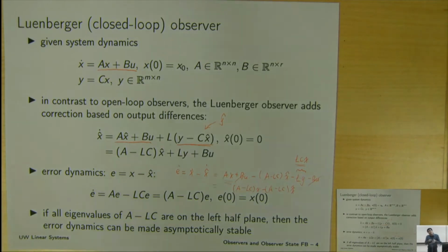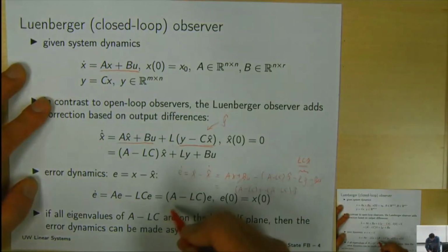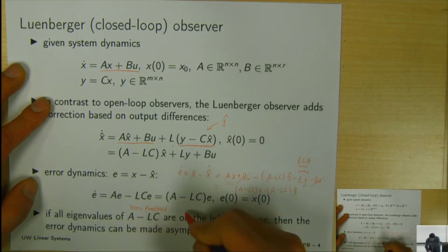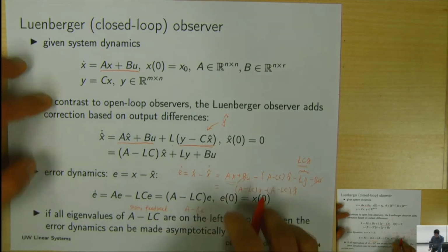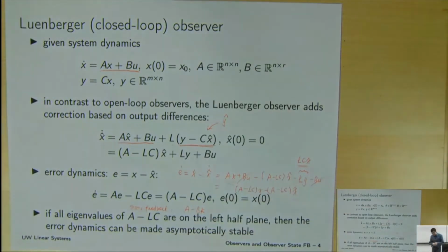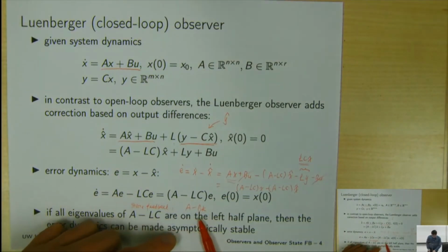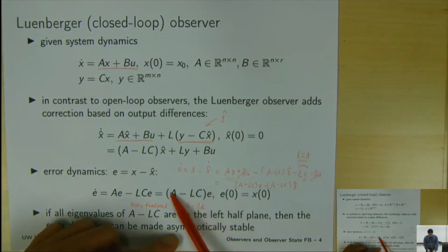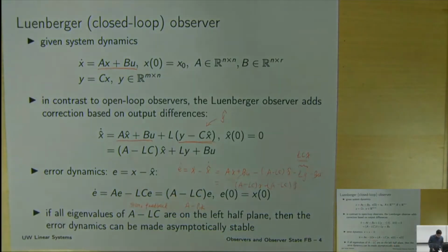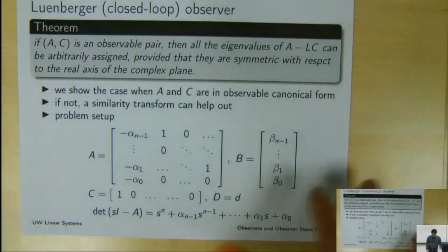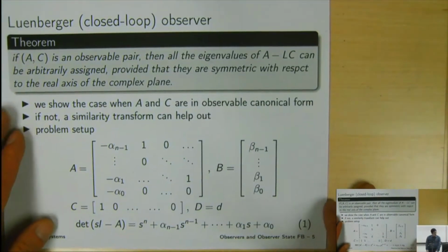All right, so this looks very much similar to the state feedback control problem that we talked about, where we were designing the feedback gain K to change the eigenvalue of this A minus BK matrix. And in the observer case it is A minus LC. We talked about duality between controllability and observability, and they show up a little bit in here as well.